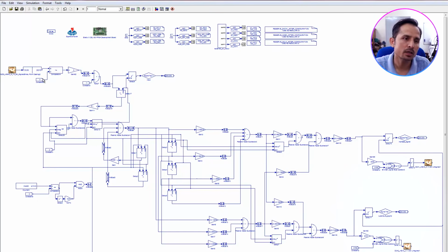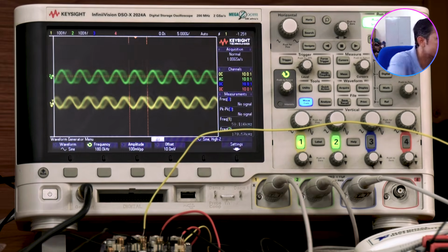First I will be giving the input to this ADC, and I am converting it to the square wave, and then this is the filter part, the comb filter, and this is the overall resonator part. This one is generating the sampling frequency, which I have already told, 50 megahertz divided by 20. So it is reducing the frequency and giving me the sampling frequency, which has to be fed to all the delay blocks, working as an enable signal. So let me generate this signal,